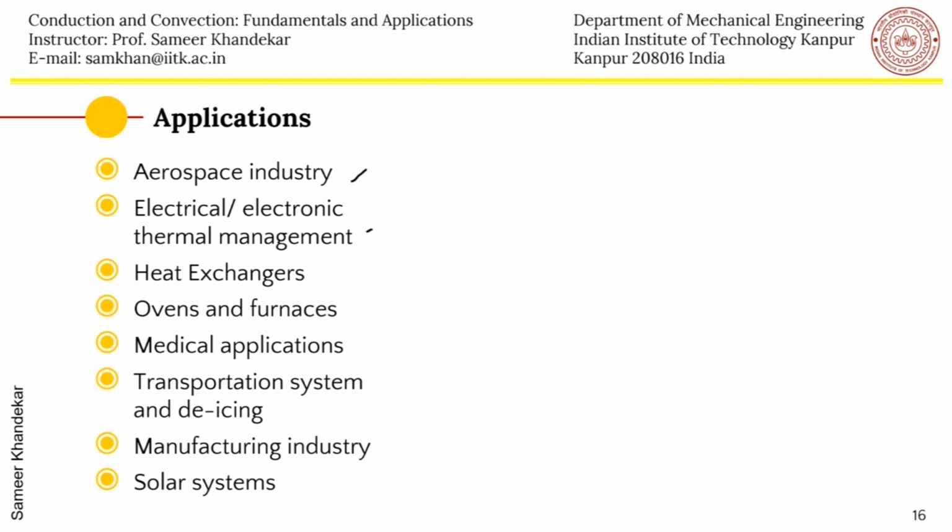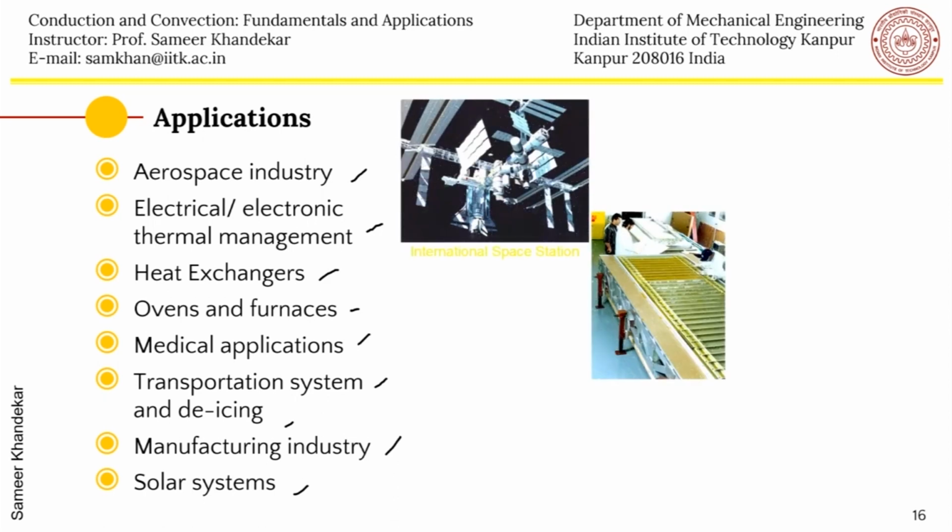So you can see the International Space Station here, and it has these deployable radiators, and a lot of heat is generated in many of these subsystems. This heat is brought to the radiators, and inside the radiators you can see these cylindrical heat pipes to isothermalize and spread the heat on these panels of the radiator.